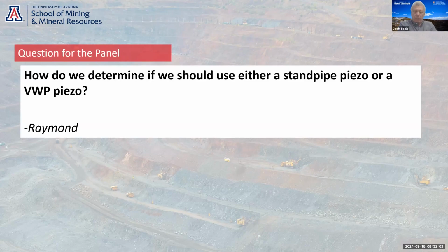So get as many water levels as possible in the early stages of a project, when you're just drilling exploration holes and when the project's still at concept level or in an early stage. Just get as many water levels as you can, and put in standpipes in open holes, or just measure water levels in open holes. The more water level data you can get, the better you'll understand the site.